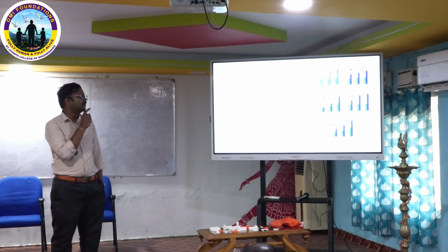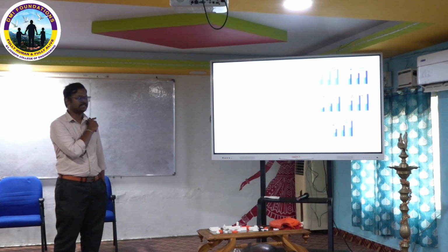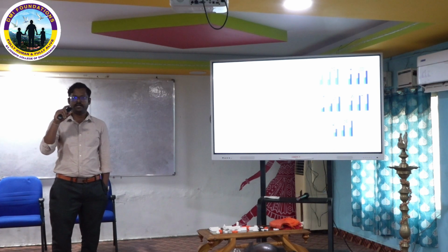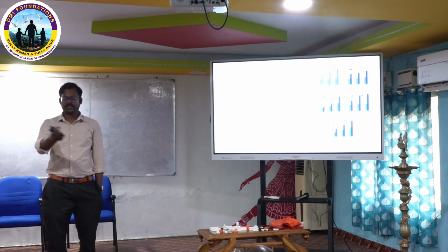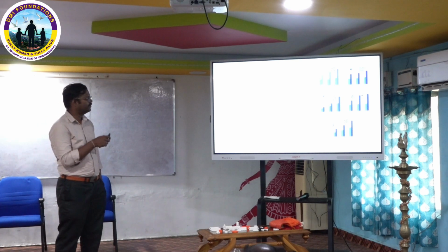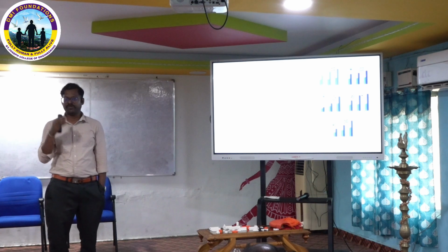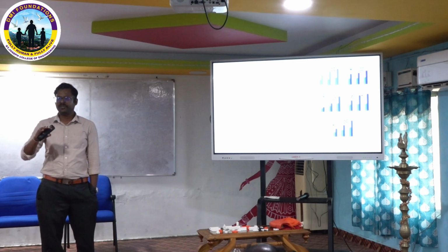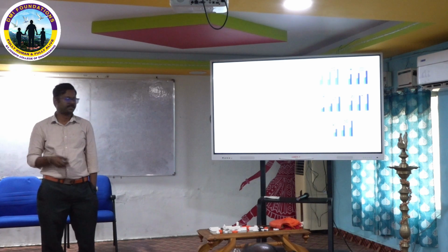In that I observed that Kelvin structures, which have vertical and stiff struts, show more natural frequency and lesser damping ratio. The structures with bending-dominated behavior, which are suitable for energy absorption, have lesser frequency and more vibration damping characteristics.